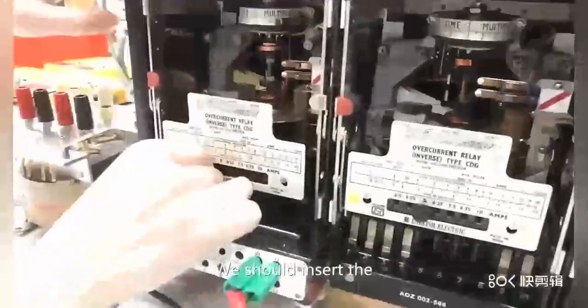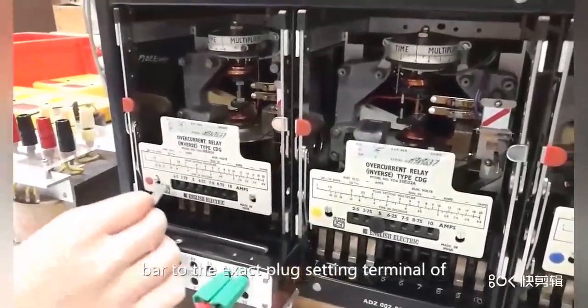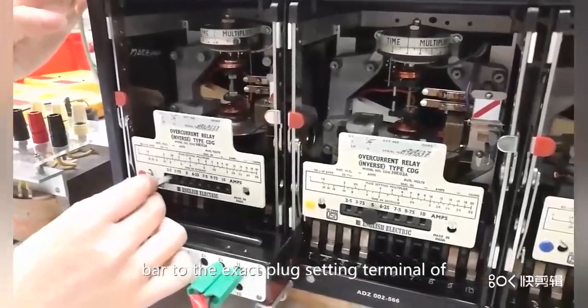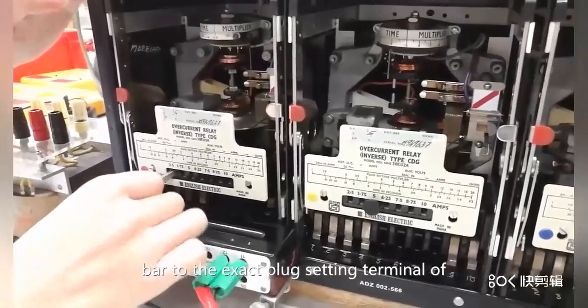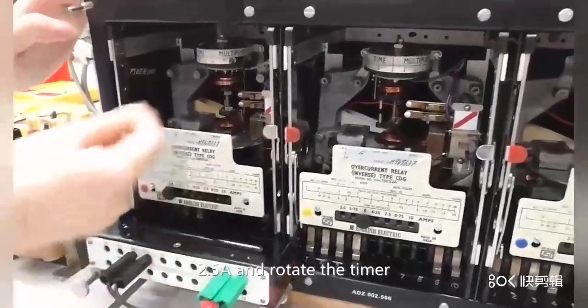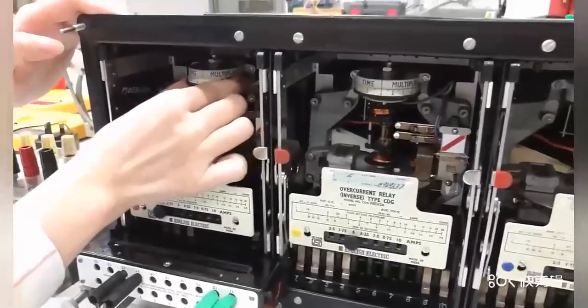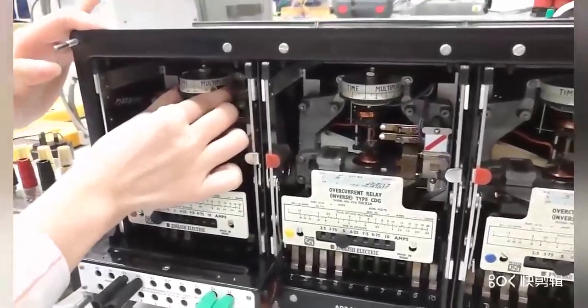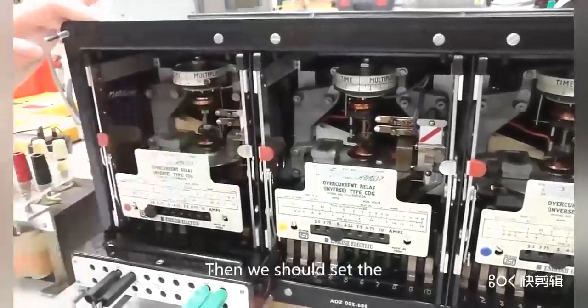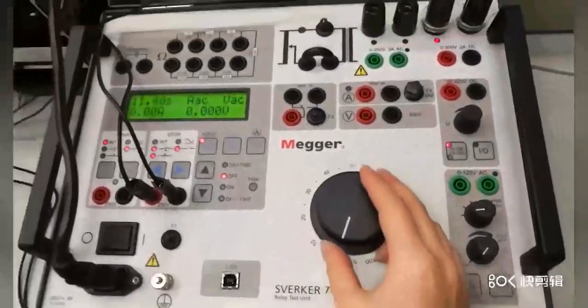Then we should insert the bar to the exact plug setting, 2.5 amperes, and rotate the timer to 1. Then we should set the injected current.